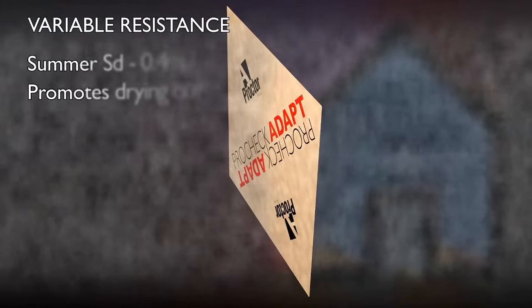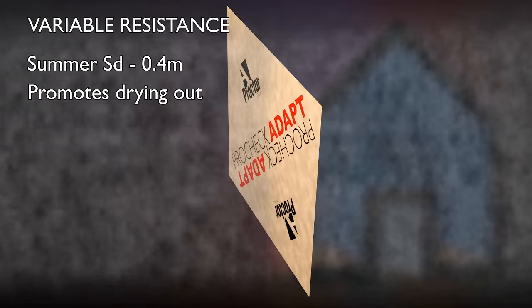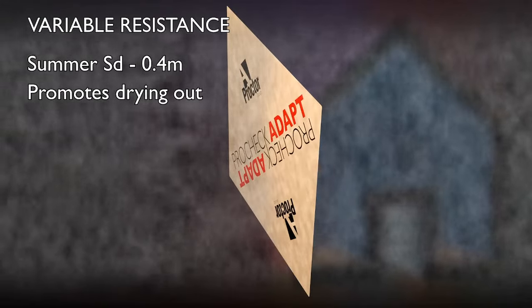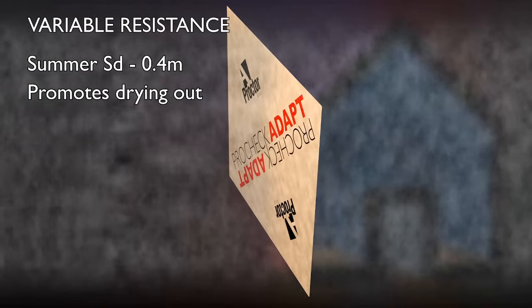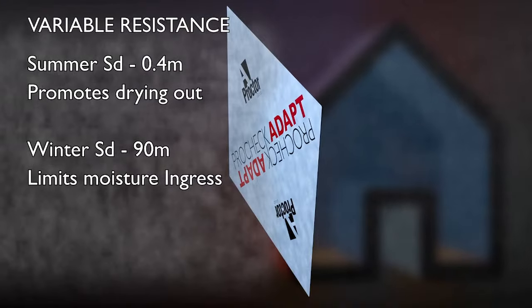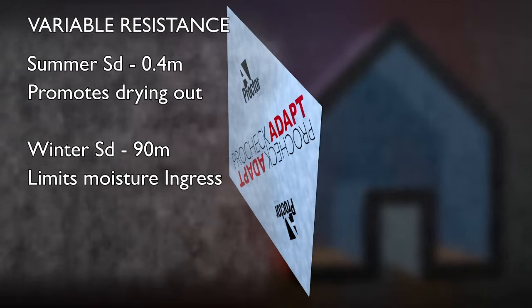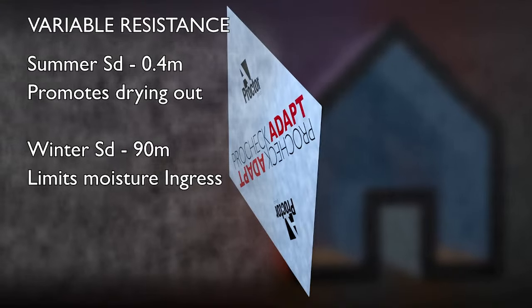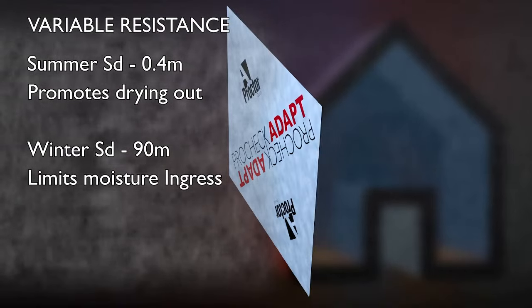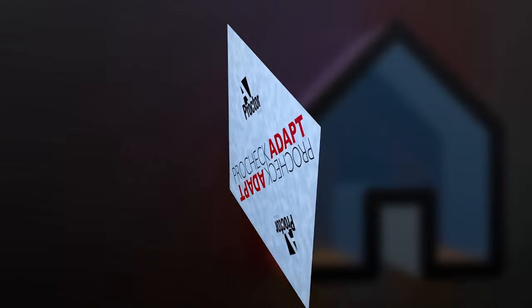In drier summer conditions, the membrane vapour resistance will be relatively low, with an SD value of just 0.4 metres. This permits moisture to pass through to a greater degree than a typical AVCL membrane, allowing the building to breathe and any excess moisture in the building fabric to dry out. When the humidity level increases, the membrane resistance increases to an SD value of 90, behaving more like a conventional AVCL and limiting moisture ingress. This helps to ensure the optimum balance of moisture movement within the building envelope, providing a healthy indoor environment whilst minimising the risk of condensation.